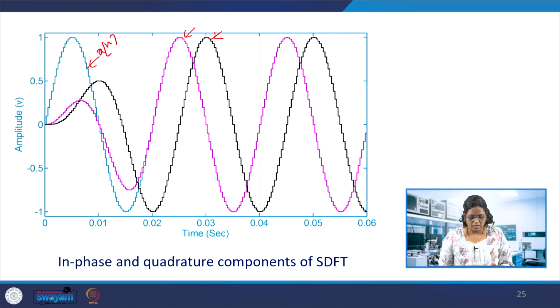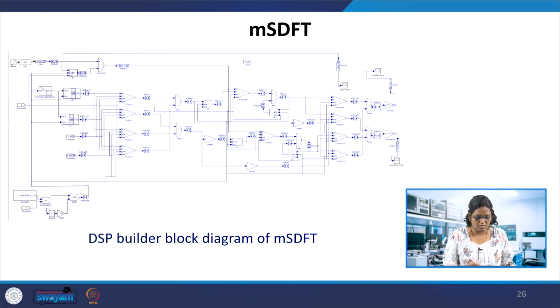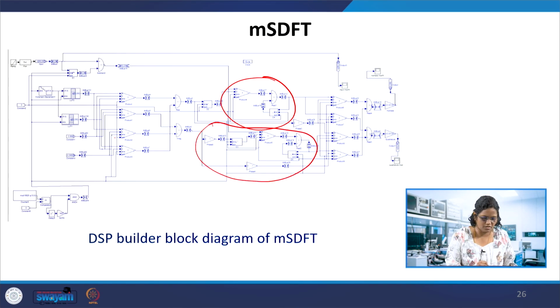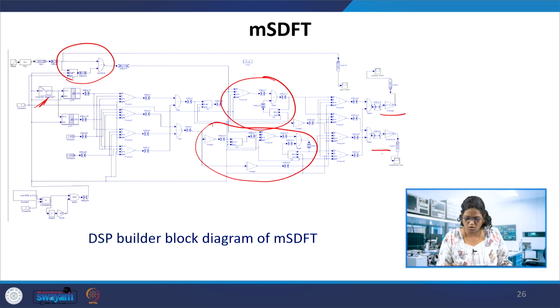targeting the FPGA. And similarly for MSTFT, we had also made these DSP Builder blocks, where you have the shifting of the 0th bin index, and we show the complex conjugate parts, and then we have used the lookup table to generate sine 2 pi kn plus j cos 2 pi kn. So that factor is here, and you have the comb filter part here.